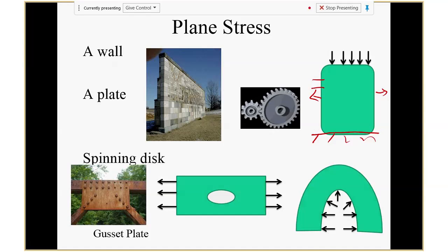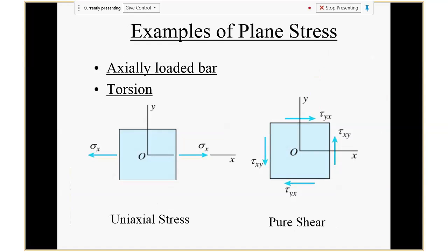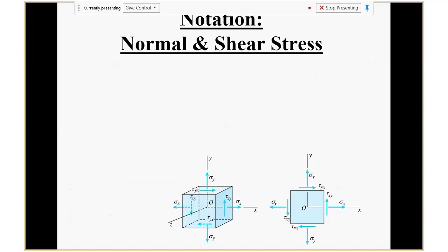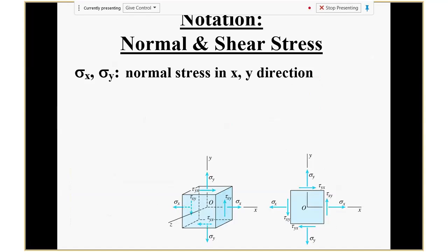All right. This one we already went over. Here is just a quick clarification about the notation, about normal stress and shear stress. First, the sign convention. When you talk about one spot, there's stress on it. If you cut the surface there, the normal stress is positive away from the surface, following the surface normal direction, and negative if it's compressive. If it presses on the surface, it's negative. That's an easy sign convention, consistent all the time during this class.